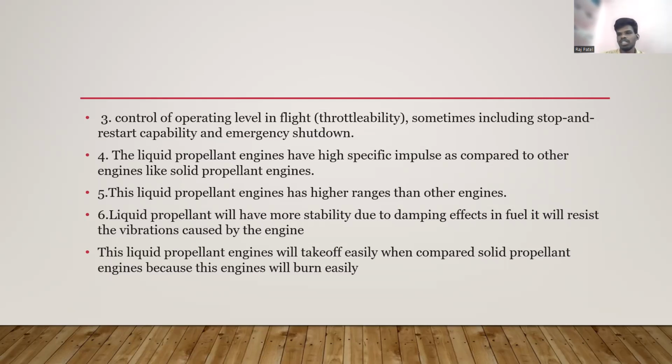And liquid propellant engines have high specific impulse as compared with other engines like solid propellant engines. As we discussed, liquid propellants have a high specific impulse, around 400 seconds, compared with the solid propellant engine. The burning rate is higher in these liquid propellant engines compared with solid propellant engines, which causes the production of high speeds and high velocities.